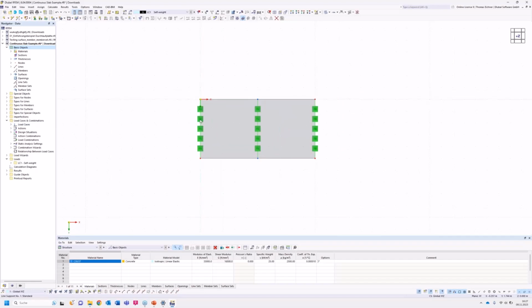This was in the presentation, I think about step 4, where we block some degrees of freedom. So we strike out some equations from the K matrix, and we also strike some degrees of freedom in the U vector. So now we have the K matrix ready. We also modified it with boundary conditions, and we have the U vector also modified, though it's unknown until after the calculation. And the last part would be the force vector.